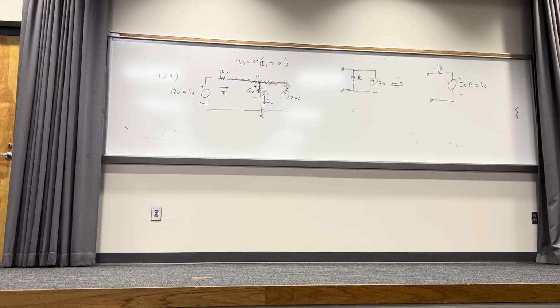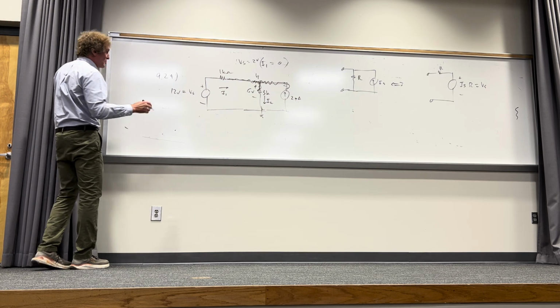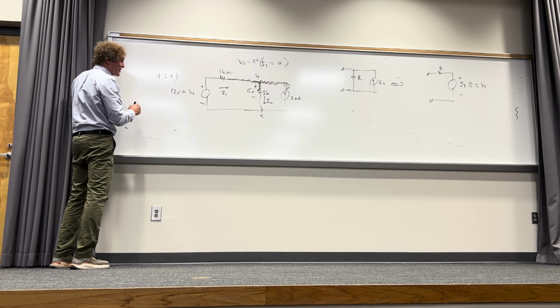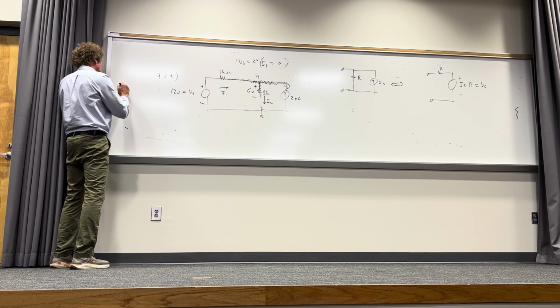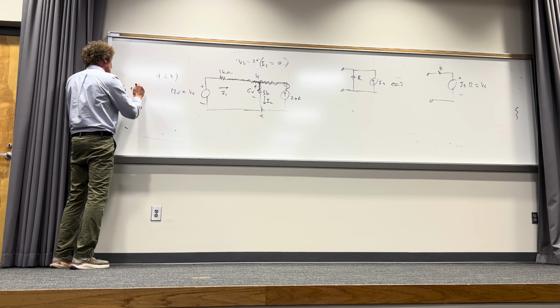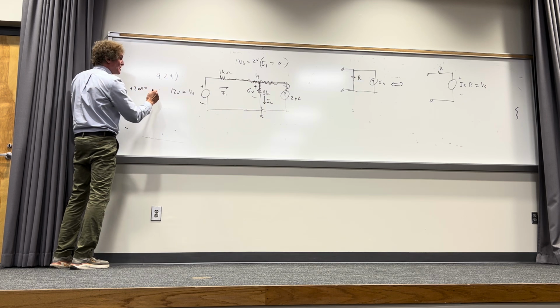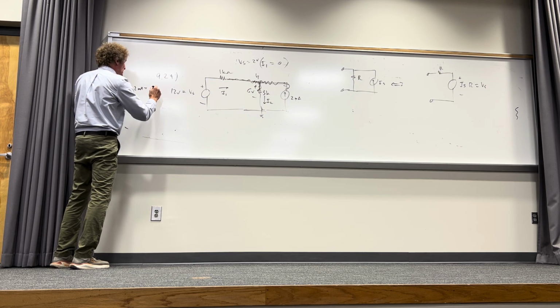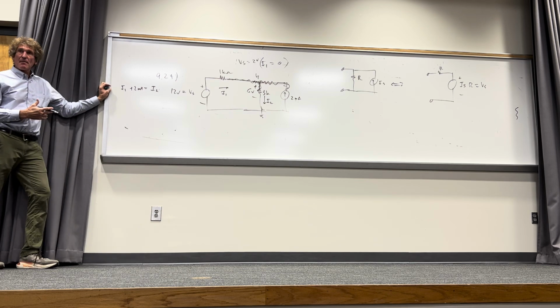And it'll start becoming clear to you what's possible. Y'all with me? All right, so for this one, if you wanted to do it with nodal, because the diode is on, we would say I1 right there plus 2 milliamps is equal to I2. I want to be clear about this. First, do you agree with that?